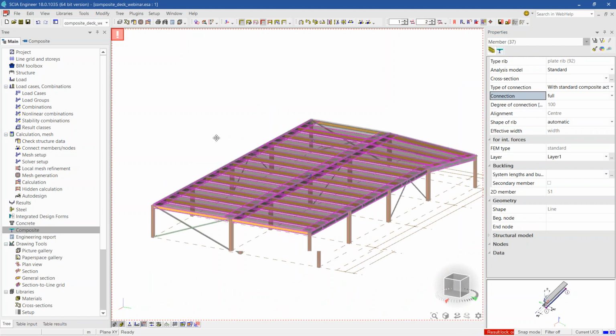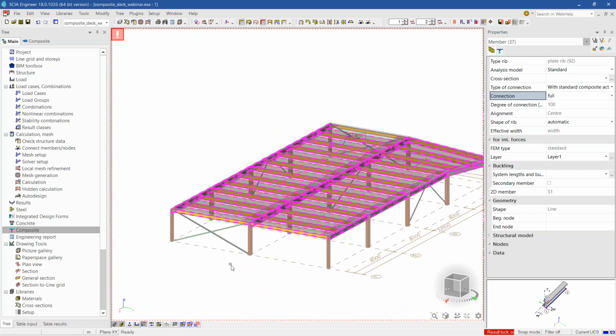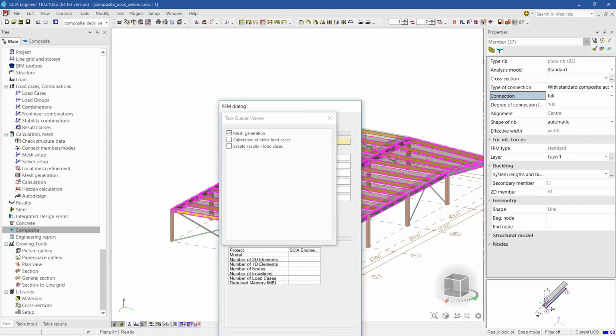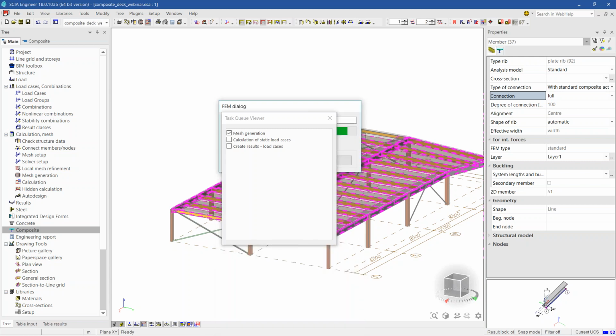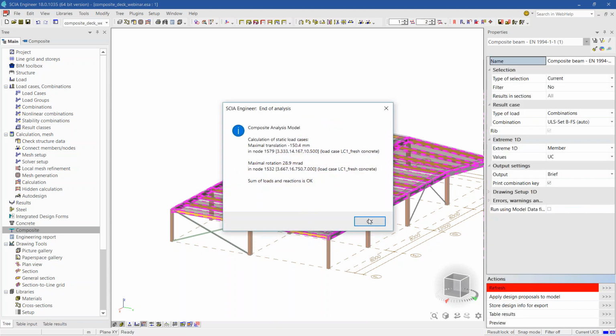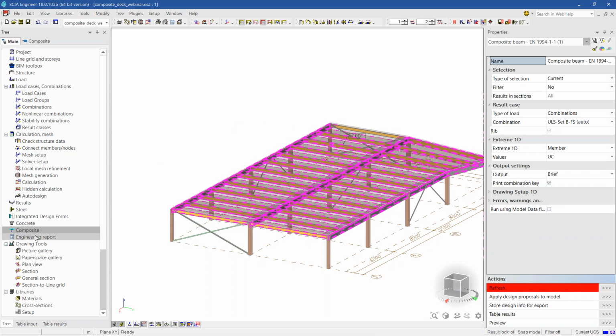Normally when you do vibration analysis, you can actually even increase the modulus of concrete to the dynamic modulus. But I will just recalculate now. And I will show you that in this case, the vibration checks will look completely different, because now you have much more stiffness, so your deformations will be smaller. And so I would advise you to run the design and then have all of your studs, cross sections and camber. And if you have any vibration problems, then save into a new name. And then do what I told you: delete all the hinges and switch to full composite action.